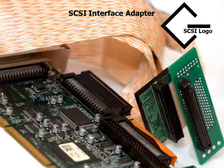With the ISA bus and the PCI bus and so forth, there's contention, and you had to hard code at one time different IRQs, interrupt requests, in order to get access to the system. SCSI didn't have that problem where you had to contend for access to the bus, because all devices were able to connect and communicate simultaneously. It was more expensive, but it was a much faster and better system than was available at the time.